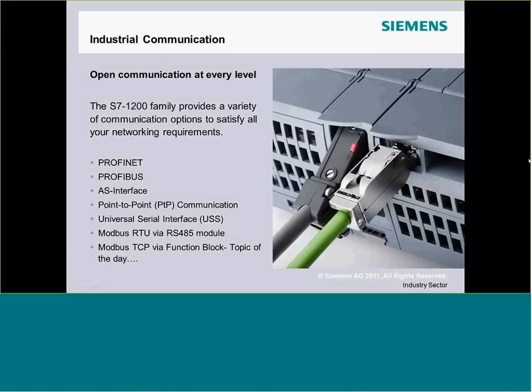The special programming cables, USB-to-serial converters, and dongles are all gone. It's capable of doing what's called Profinet, which we'll discuss in a moment, from which we can do multi-device protocols, including distributed I/Os. In this picture on the right side, you can see this green cable, which is a Profinet cable, connected to the Profinet Ethernet connector on the PLC.